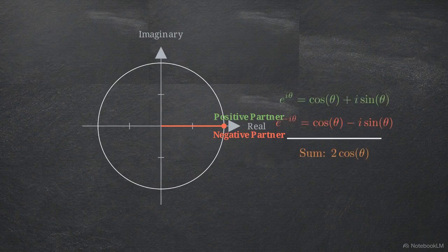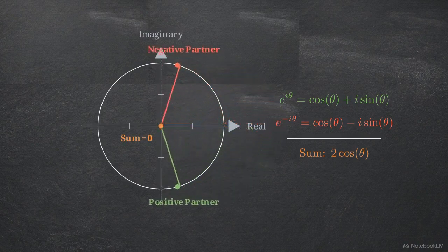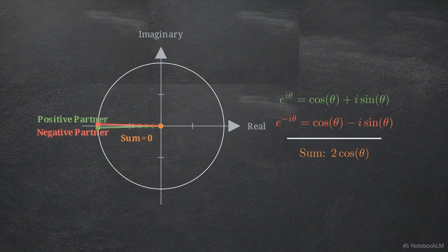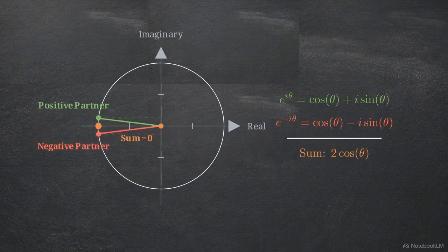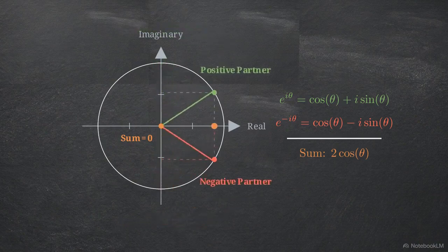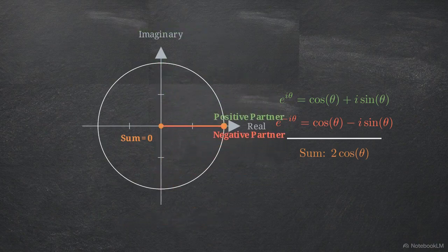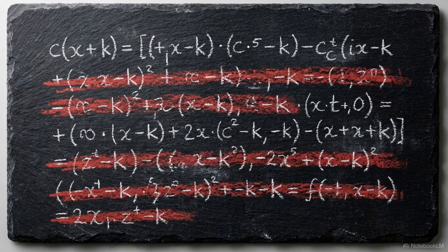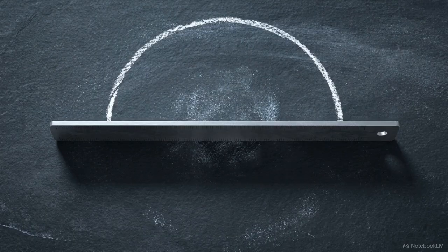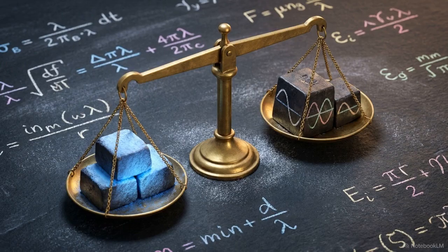To reconstruct a strictly real-valued signal, the algorithm must cancel out all imaginary data perfectly. As the two symmetric vectors counter-rotate, their vertical, imaginary movements are perfectly opposite. They sum to 0 at all times, while their horizontal, real components combine constructively. The real DFT ignores these negative frequencies by hard-coding this cancellation into its mathematics, which obscures the full rotational picture. The FFT array's upper half provides the geometric symmetry needed to cancel imaginary data. These negative frequencies act as structural counterweights, keeping reconstructions strictly real.